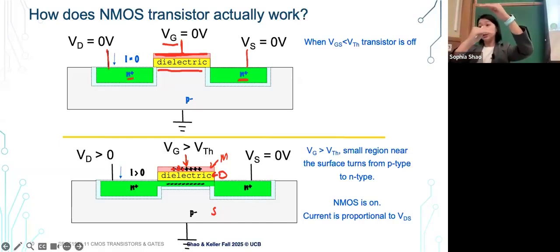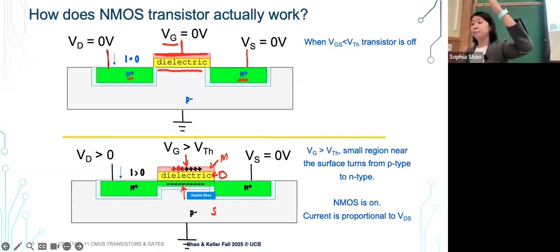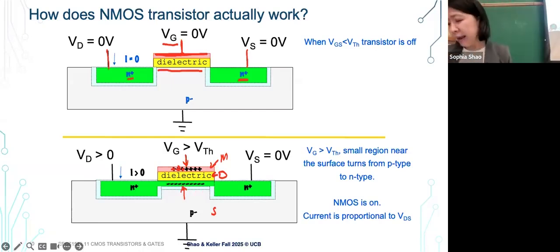It's accumulating charges. But once there are lots of positive charges on one side, you can think of the capacitor metal, what it does is attract a lot of negative charges on the other side. The other side of the metal attracts a lot of negative charges there, to the extent that once it's high enough and you wait a little bit, there are enough electrons, in this case, that they can form a channel between the source and the drain so that things can flow around.